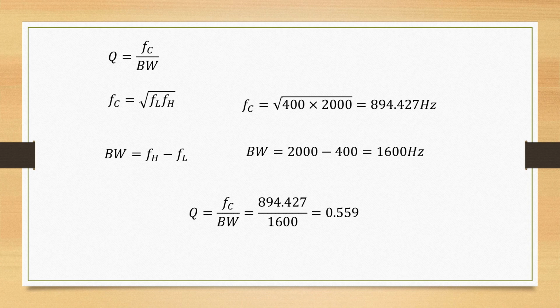As we have seen, the quality factor for a wide band pass filter is lesser than 10. In this case, it is lesser than 1. So with this, we have completed all three parts of the problem: the design part, the frequency response, and finding the quality factor.